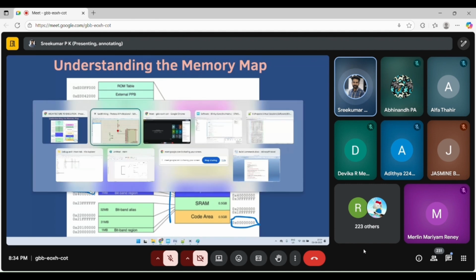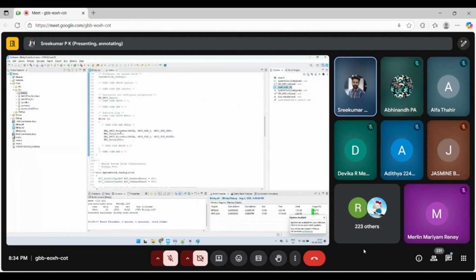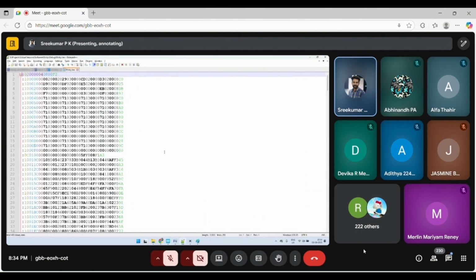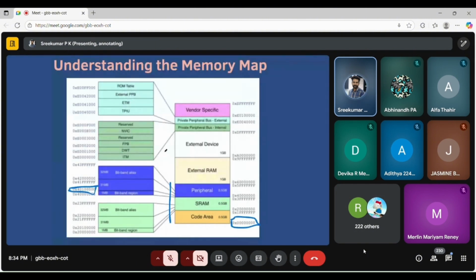So you can see this code. GPIO write pin set, GPIO write pin reset. In between there is a delay. So there is someone who is converting this high-level logic into low-level machine code. That is the compiler and its associated tools. We are slowly moving to those tools. But before going to those tools, you have to understand this internal concept, what is actually happening.